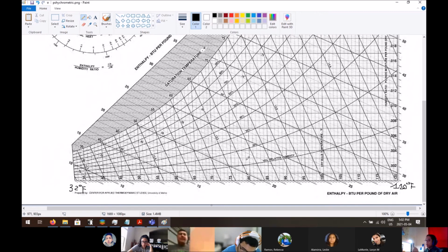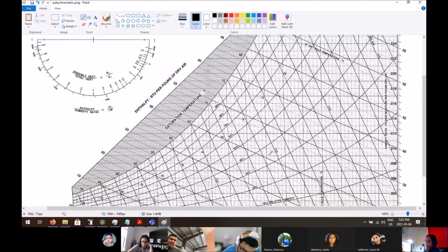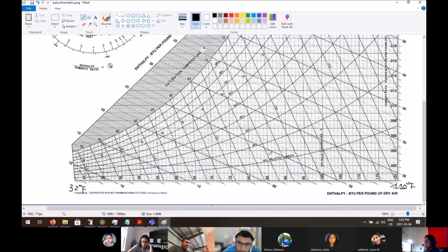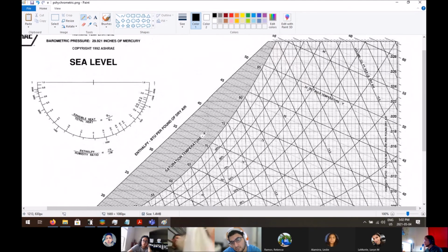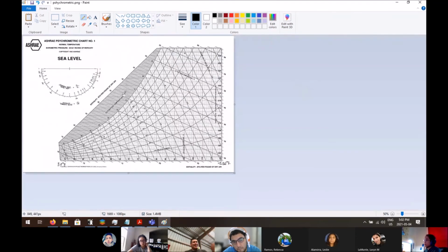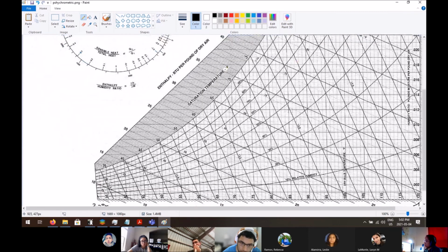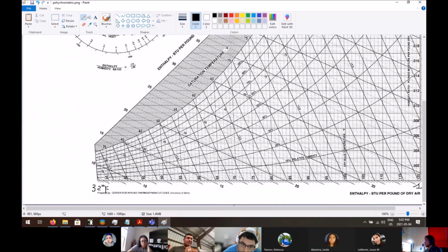Right. So now you have humidity. Whenever you get a weather forecast, you're given temperature, of course, and that's going to be your dry bulb temperature. You're also given a humidity, and that's normally given in a percentage. So you see these sort of curves right here. Go like whoop right there, swoop right there. That's going to be your relative humidity, right? You see right here, this line represents 90% relative humidity. 80, 70, 60, blam, blam, blam.